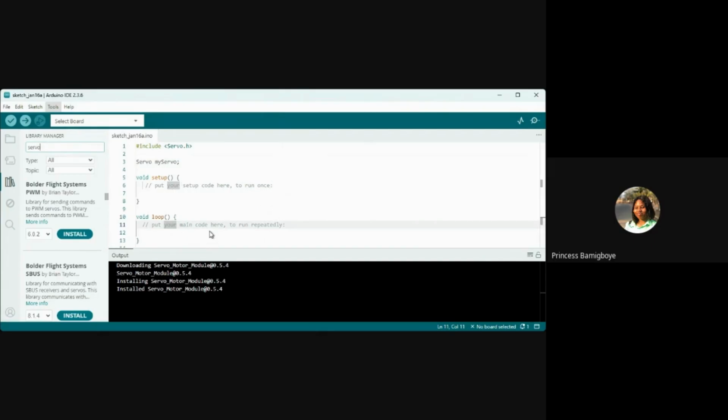Then if we import more boards like the ESP32, which I keep mentioning, you'll never forget it. You see different types of ESP32, ESP32 C3, ESP32 S2, C3 Pro Mini, all of them. Then reload board data. Maybe you want to flash and reinstall. Then get board information. Then burn the bootloader, meaning you want to install the OS. That's like the bootloader, the software.